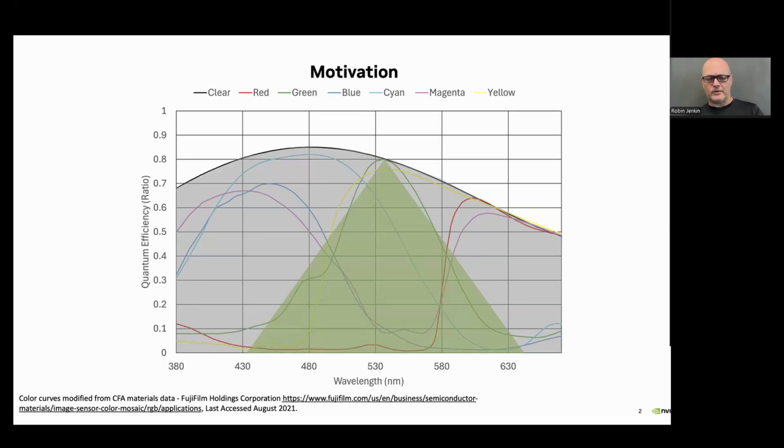And of course, that's important for automotive systems because we want our cars to drive us at night, and we're just relying on headlamps to illuminate the scene. With an inverse square law falloff for our headlamps, very rapidly we lose range, and that limits the highest speed at which we can travel.